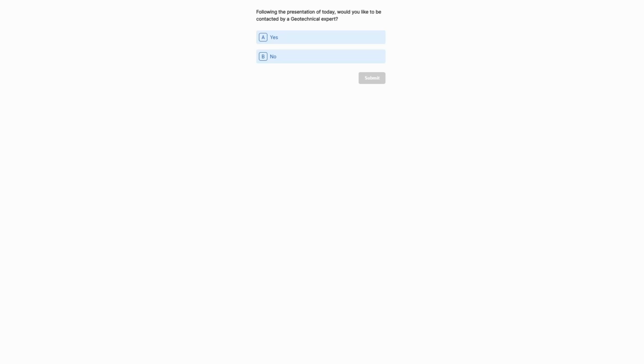Just do a cross-section over the width of the bottom of the excavation, over the length between the symmetry axis and the inner part of the retaining wall. By doing that cross-section, Plaxis will automatically perform an integration of the water flow along that line. The integration of the water flow along that line will give you the discharge in terms of volume per unit of time, in days here. That's the way you do it.